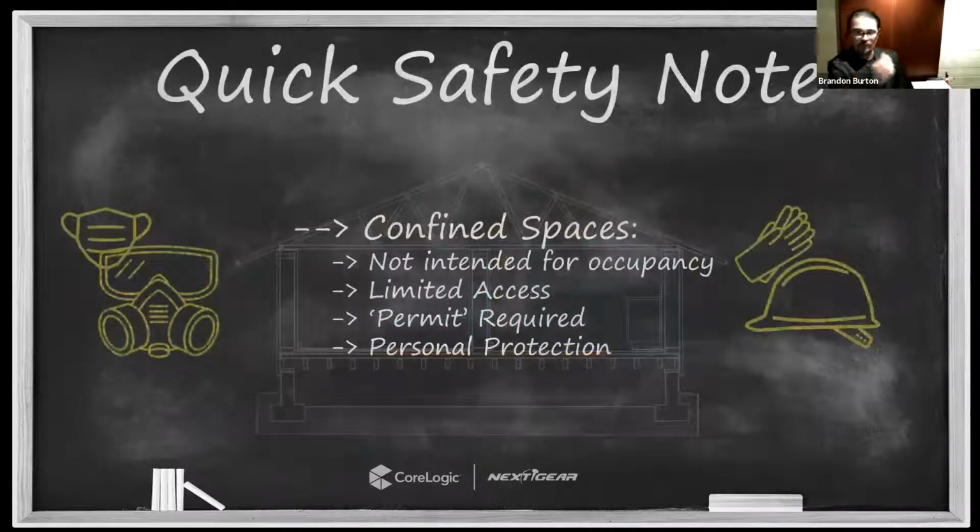As we go there, I've got to start with a little safety meeting, of course. Always begin every conversation with a quick touch on safety. Some of these spaces are technically what we would define as a confined space. I'm not going to get into OSHA and regulation and all of that. I just want to ensure that you have awareness that when we are dealing with a substructure or really any space within a structure that is not intended for occupancy, that has limited ingress and egress, in other words, it's not real easy to get in, it's not real easy to get out, generally these spaces are what we call permit required spaces.